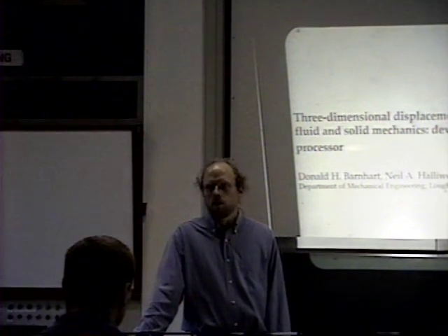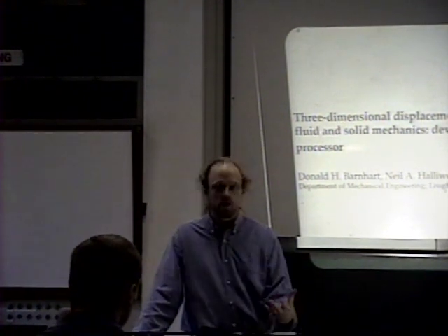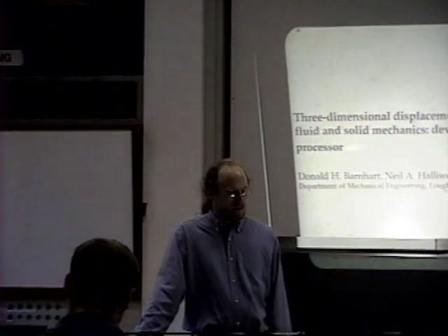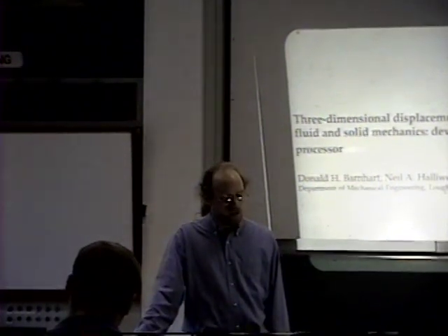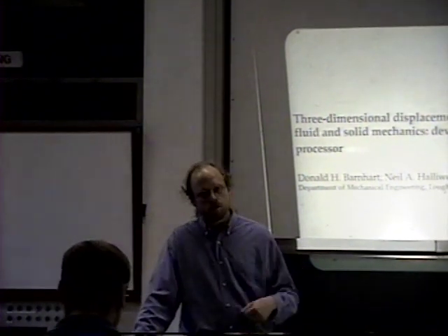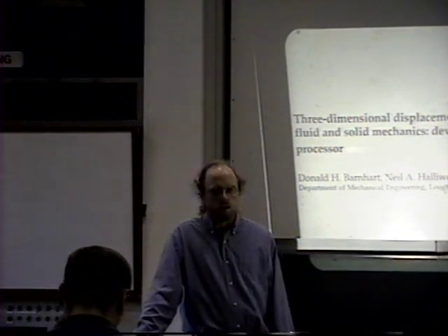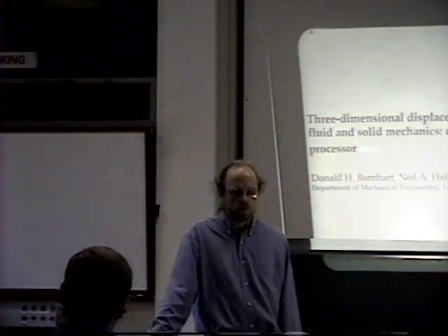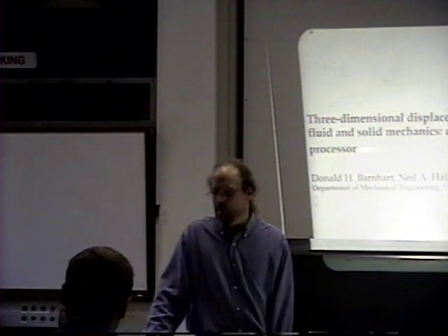Hopefully all of you are pretty well aware of what particle image velocimetry is and the basic ideas behind it. What we are doing is extending this into the third dimension and using a hologram as a recording medium instead of a two-dimensional, planar camera.